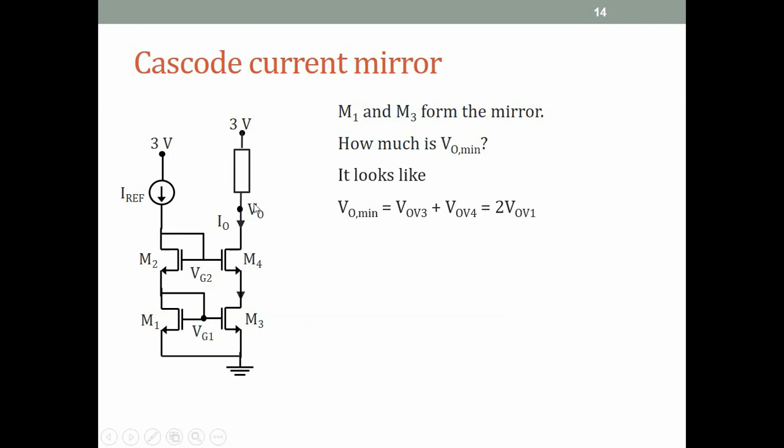All right, so this is the Cascode current mirror circuit. And as I said, this was used for many years. Now it has been replaced by another one, which we'll see after we discuss this circuit. Okay, so let us find its performance parameters. We already saw that the R out is gm4 ro4 ro3 plus ro3 plus ro4.